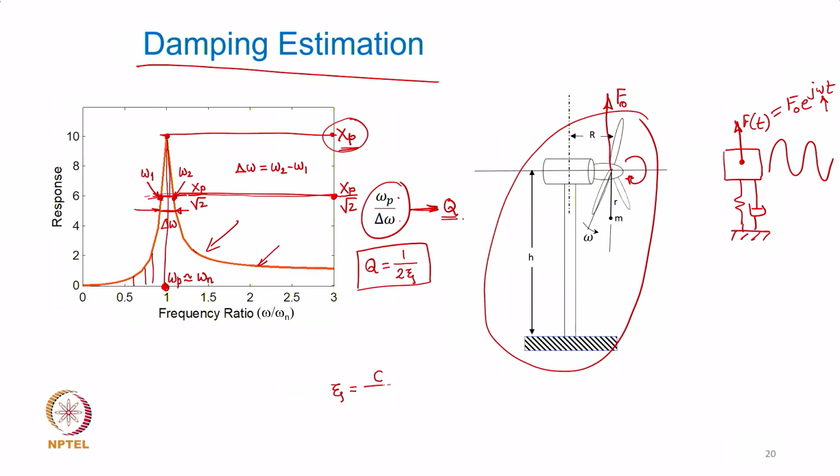You need to know what the actual damping in your system is, and Cc, that is the damping factor. Now, if I ask you to find out the damping factor for your system, you will first figure out what the quantification of this damping coefficient is. You never know in your vibratory system, if there is no dashpot, where that C is coming from, right?